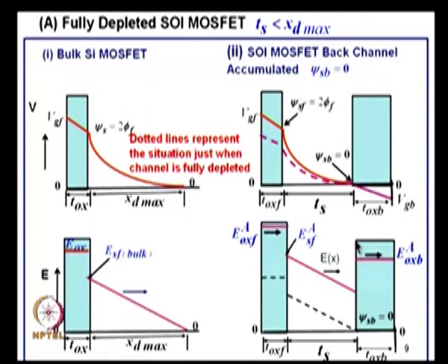So, if I draw the electric field here, I fix the voltage as V g b, there will be an electric field like this. There will be charge here, plus charge here, minus charge here. This plus charge can be very large because doping is large there, and this will be negative charge. Now, when you started with that bias fixed, we are not varying that voltage, we are not varying the field. When I apply voltage to the front gate, what happens initially?